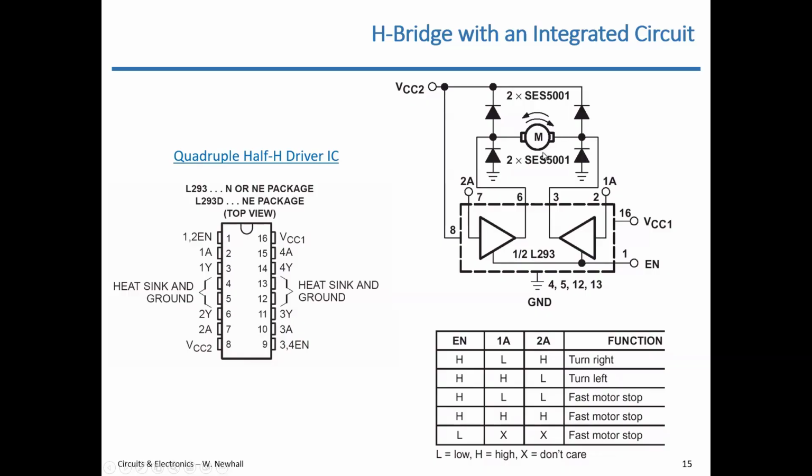Remember we talked about the voltage across an inductor. Voltage is equal to L di/dt. Motors have coils in them, and coils have inductance. So if you try to shut the current off through a motor very rapidly, you get a big spike of voltage. di/dt is large. What these diodes do is they conduct current when that spike happens, and they dissipate that power. They absorb that power.